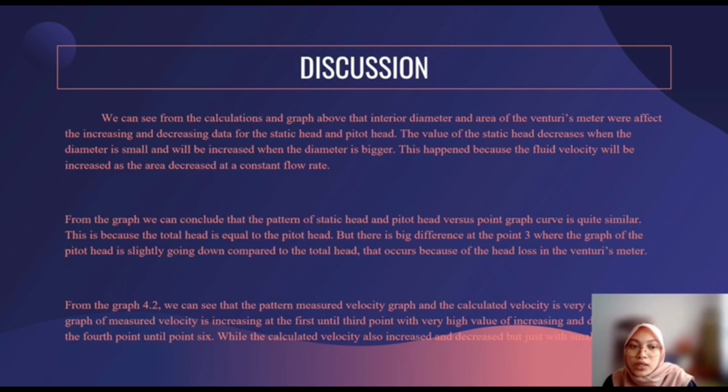rate. From the graph, we also can conclude that the pattern of the static head and pitot head versus point graph curves is quite similar. This is because the total head is equal to the pitot head, but there is a big difference at point 3 where the graph of the pitot head is slightly going down compared to the total head. That occurs because of the head loss in the venturi meter.